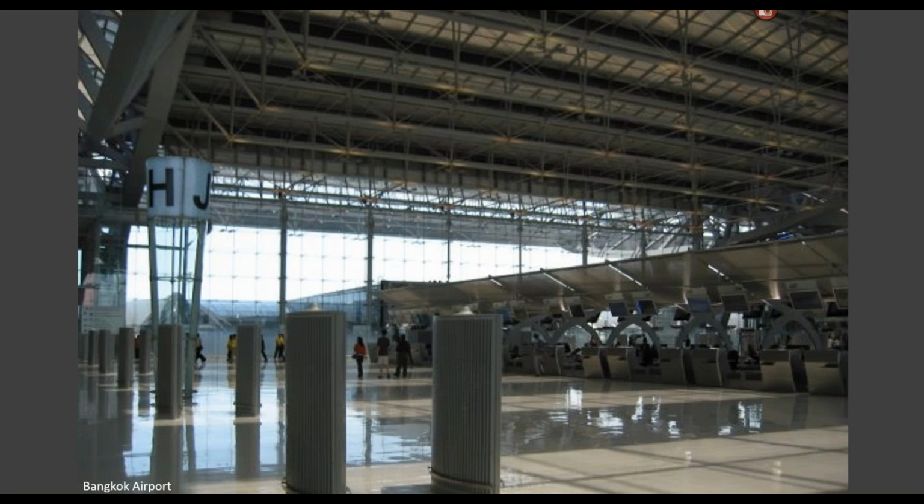Here's a great example of displacement. This is Bangkok Airport, and we have these blade style displacement diffusers that discharge on both sides. And so we have a very, very large high ceiling space, glass walls. So introducing air from the glass wall would be very difficult. Introducing air from the ceiling would be very difficult. So displacement for this type of application is actually ideal over traditional overhead because we're introducing the air right at